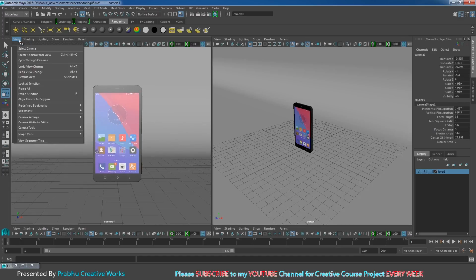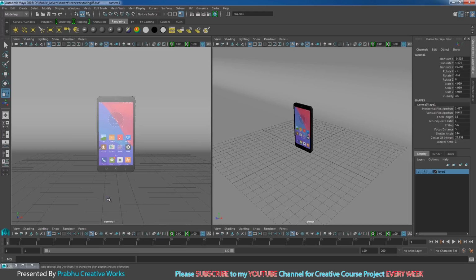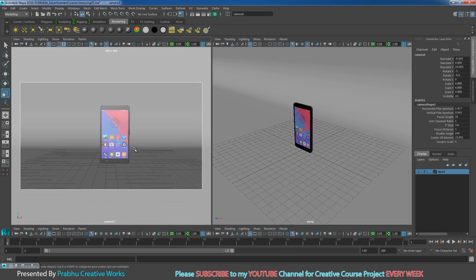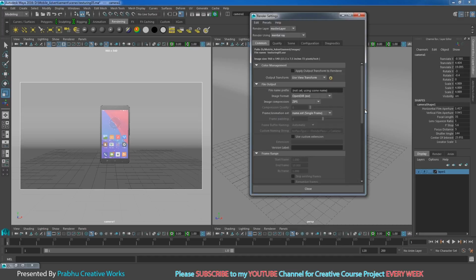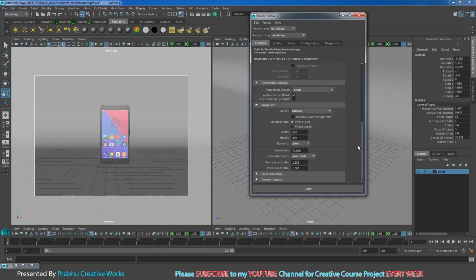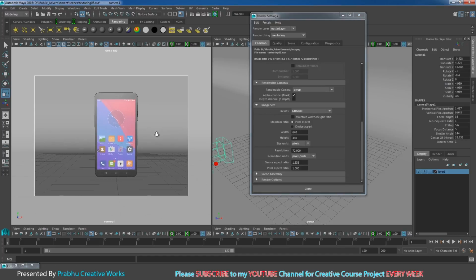Now go to view, camera settings and choose overscan, and go to view, camera settings and choose resolution gauge. Here by default we have 960 by 540. The image width and height is too high when you start lighting. So before we start lighting, you need to go to render settings in the common tab. Here you need to set the image size to 640 by 480. It's enough for when we start lighting. I will zoom in a little bit like this.